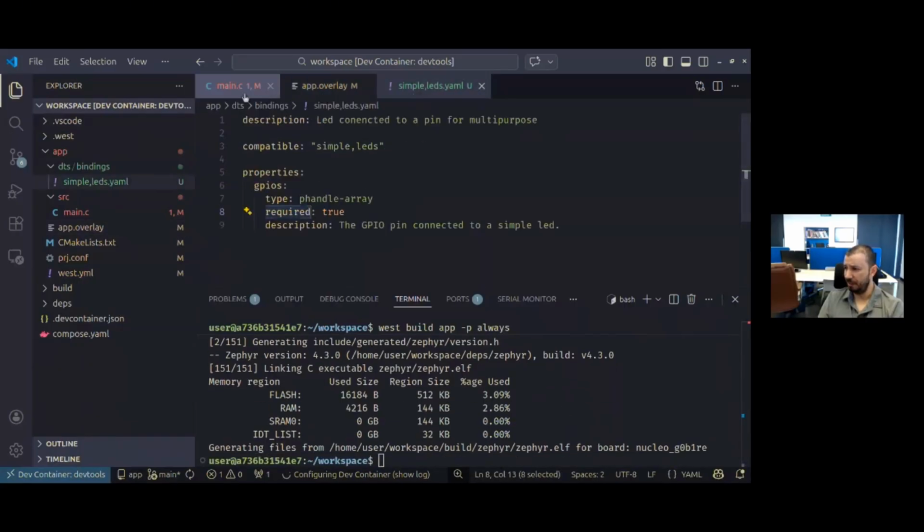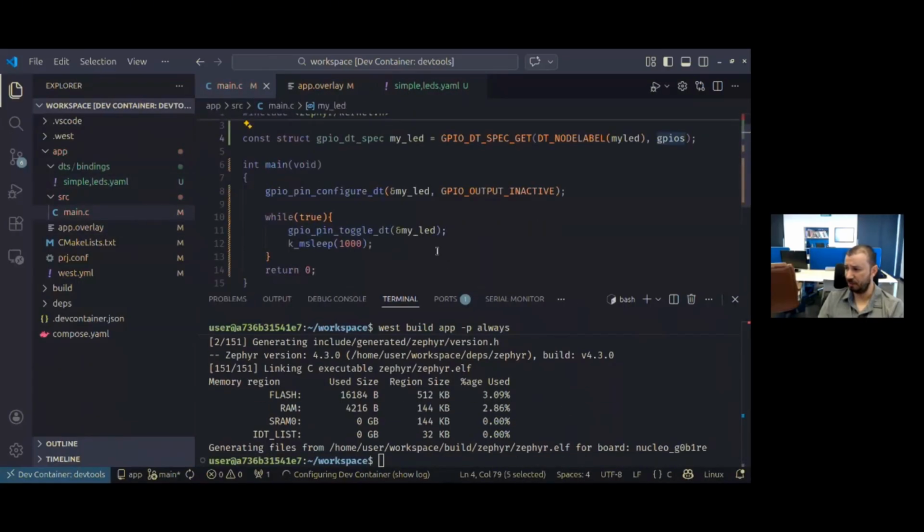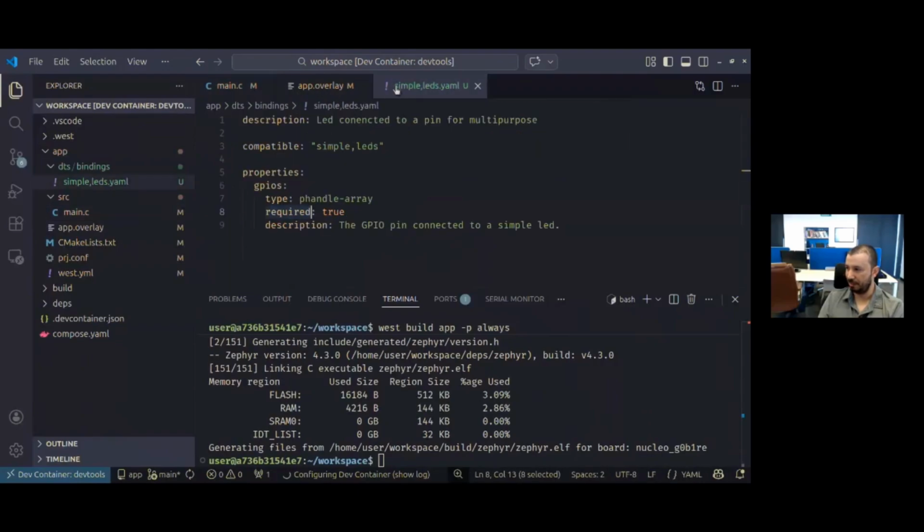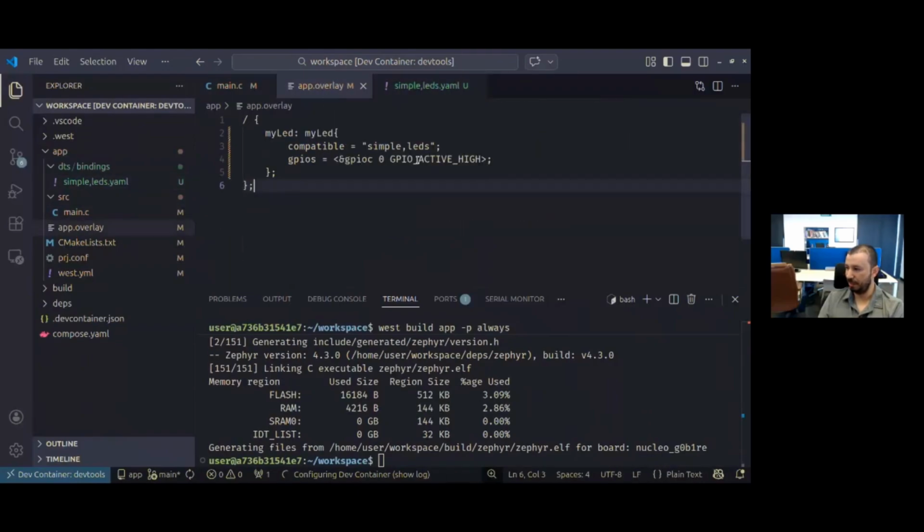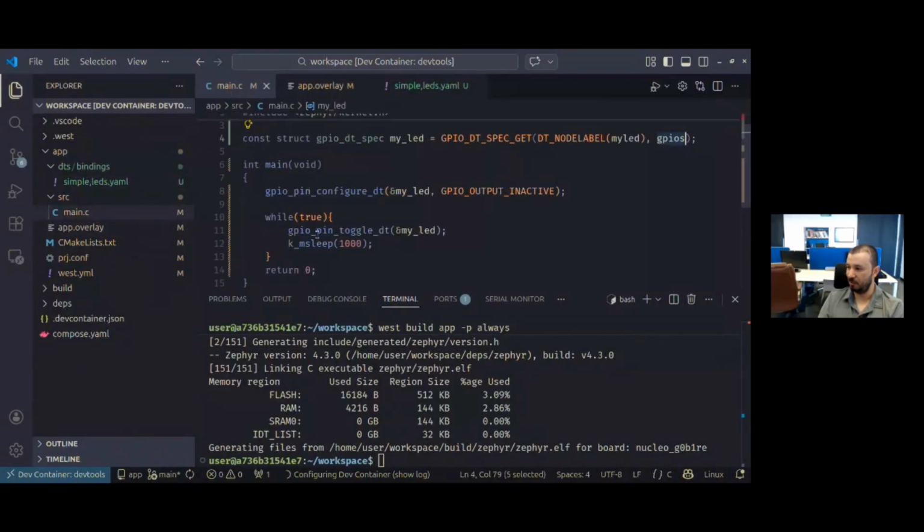So in theory, if I flash this program, we are going to see the LEDs starting to blink every second. Right. With this macro, we're extracting the property GPIOs, which basically are these values for pin and flags, and that's what the driver is going to use in these specific functions. So we're not making a new driver right here. We're just limited to writing a binding file.